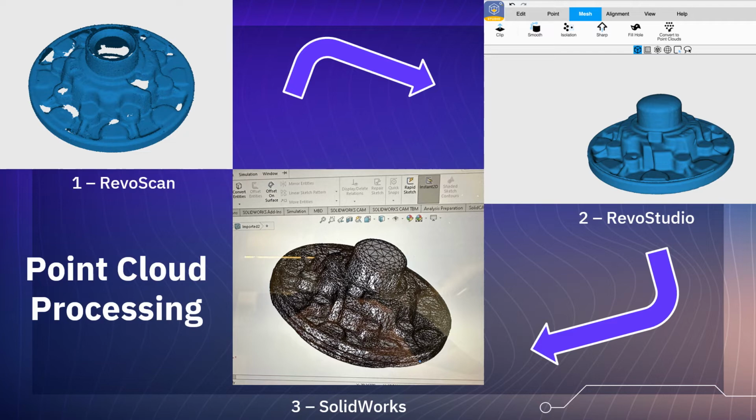The hole filling feature automatically detects and fills in any holes on the surface of the part file to ensure it is a complete geometry. Simplify. This function eliminates unnecessary point cloud data that does not improve the accuracy of the scan. This function can also reduce the number of polygons in the mesh file while retaining as much detail as possible. This feature is crucial in minimizing the size of the part file so it is compatible with CAD software. For SOLIDWORKS software, it is ideal to have a maximum vertex count of 20,000.